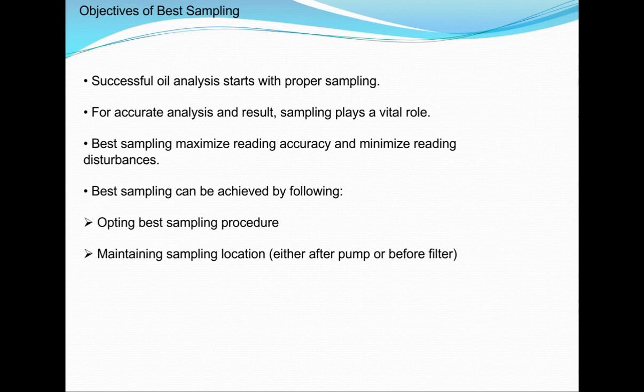We have to see that the sampling point should be either the discharge of the pump or before the filter. This is the best point for taking a sample. Another thing is the apparatus, the bottle in which we are taking the sample. That apparatus must be in a clean condition. I will discuss in the next slide what the cleanliness of the bottle is and what the limit for that should be.